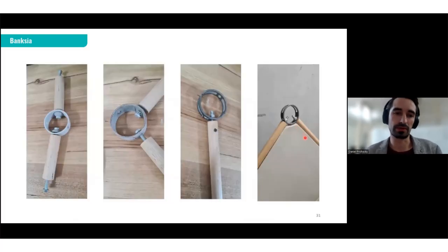We went through this process of prototyping. So the connections, for instance, we wanted to make all modular. This is just a PVC pipe, cut to get the geometric shape, and a few coach screws. And then looking at threaded inserts and a bolting steel ring. Then these two methods just being manual, and then tube laser cut, precision laser cut with a threaded bolt and